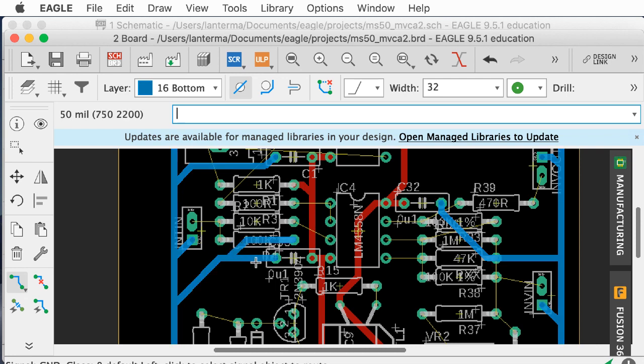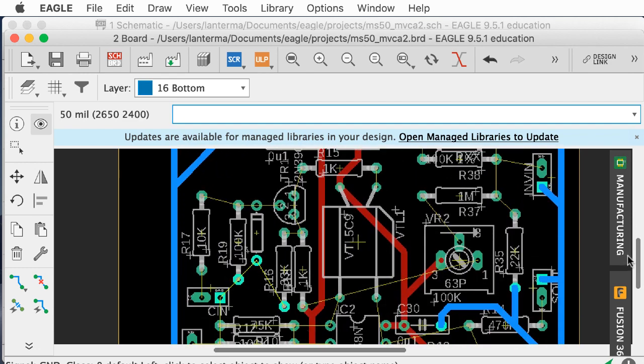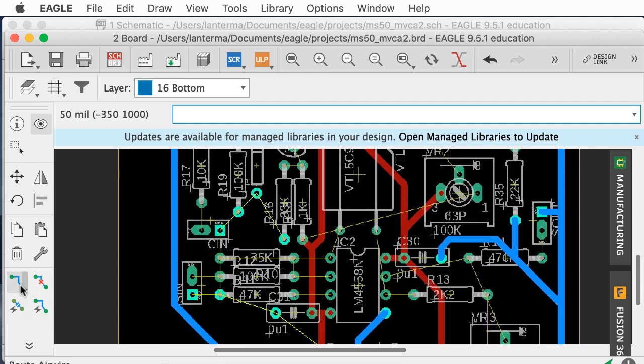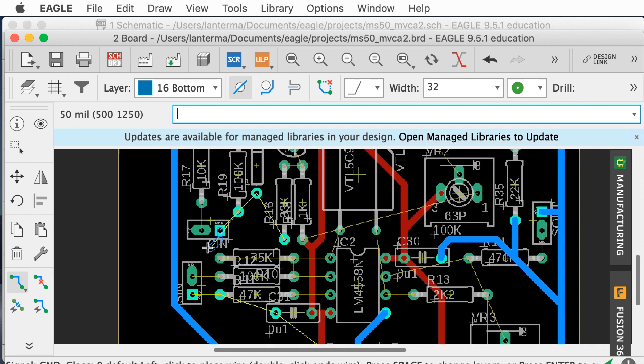Now, you could make an argument, is there a capacitance between these two traces that would create a problem? I don't know. These guys need grounds. Okay, that's a little tight, but it still works. There should be enough clearance here.